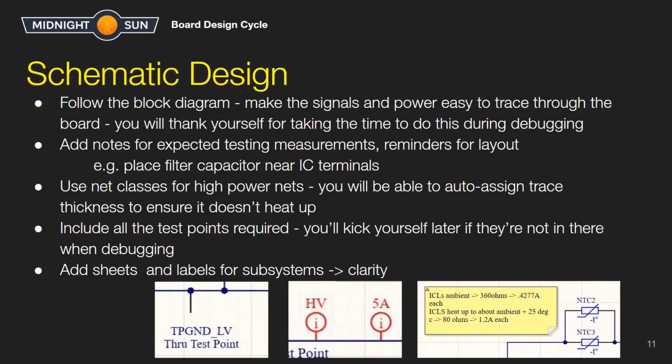For sheets and labels for subsystems, it's very easy to separate your schematic out into different sheets. If one sheet deals with high voltage, leave that all in one sheet so that any high voltage systems are easy to debug and you have it all in one place.